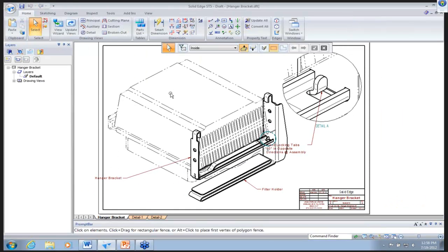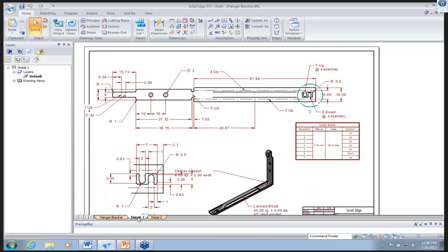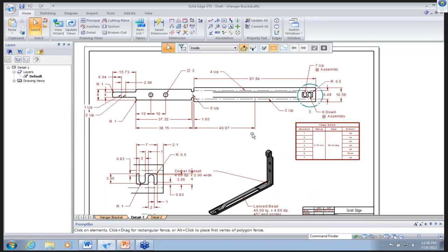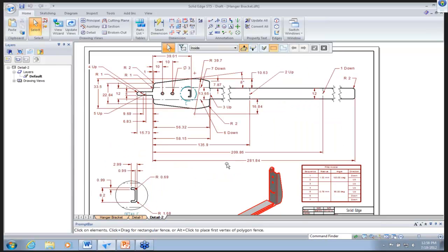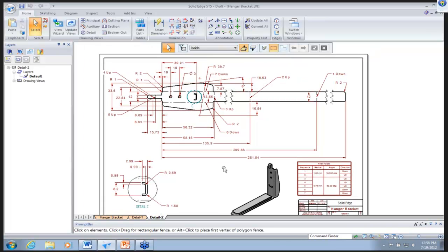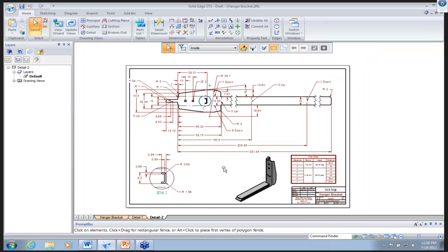So you can still see the heat sink since this construction is kind of a phantom lines there. Here's our assembly with all of our features we created. You can then create other pages with the flat patterns of the sheet metal parts, calling out the different bend sequence and everything. Same with our other part here. And we'll get more into drafting in the part 2 Lunch Byte.